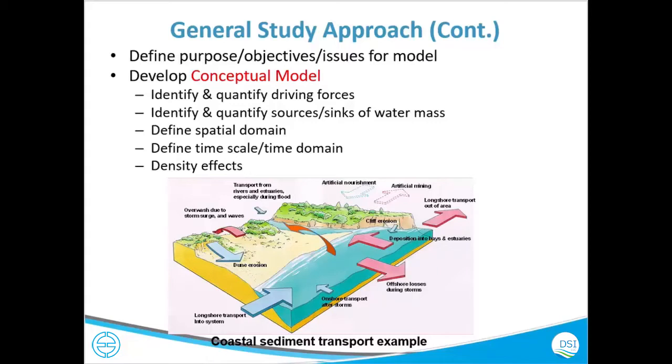Then you need to know for what time you want to run a model. Is it for 2 years, 3 years? Is it for 10 days? Those are the things you need to consider. And density is always an important factor in modeling. Be it temperature or salinity, density will become an issue. So you need to consider those kinds of things.